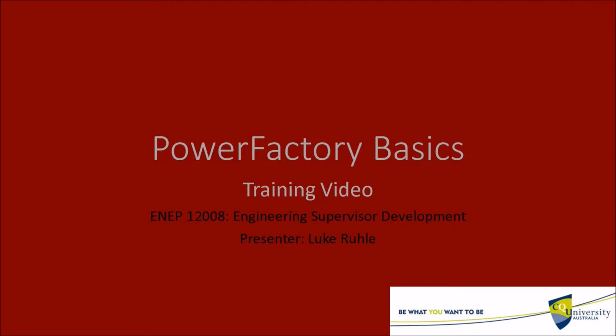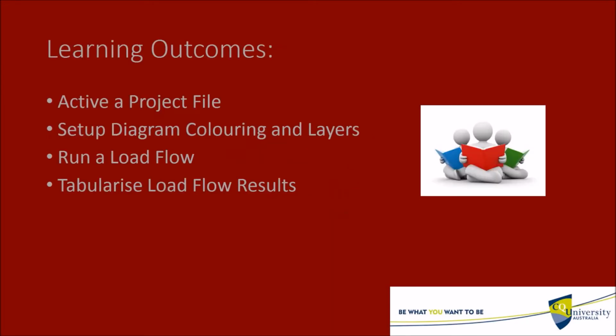Today I'll be presenting a training video on the PowerFactory load modelling software. After this video you should be able to activate a project, set up diagram colouring and layers, run a load flow, modify the graphic window and tabularize results.